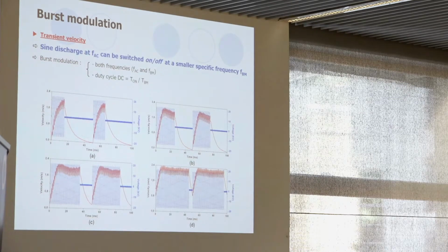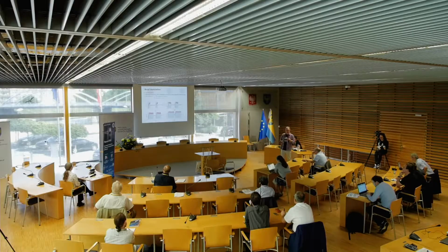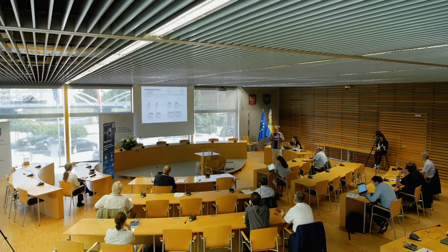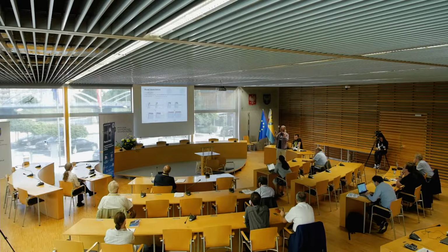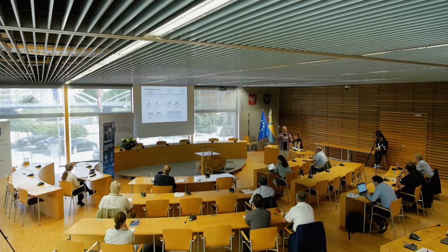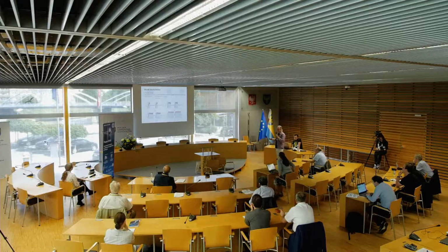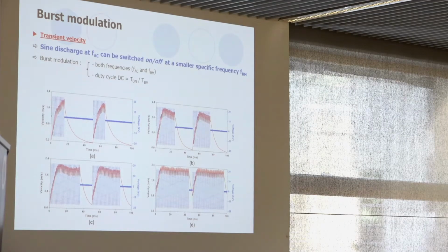Moreover, we can switch the discharge on and off, meaning that we can have two frequencies in the produced wind. In fact, we can have the spectral signature we want in the wind. For example, in fluid mechanics, if you want to produce a wind with frequencies in a given bandwidth, you take this bandwidth in frequency, do an inverse FFT to get the signal that is going to energize the high voltage power supply, and you apply the given waveform, which will produce the wind you wanted at the beginning.